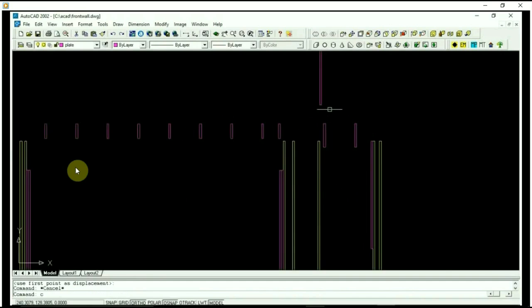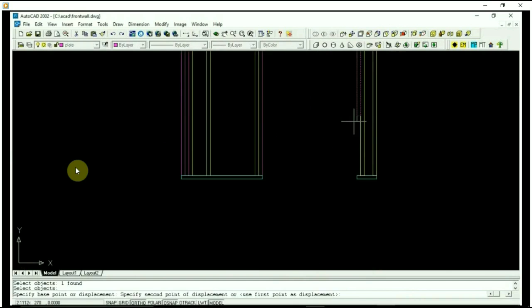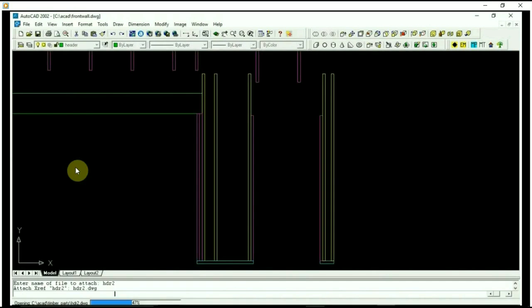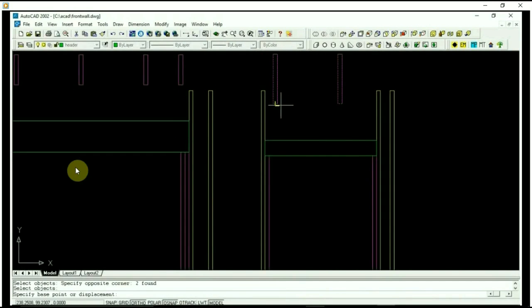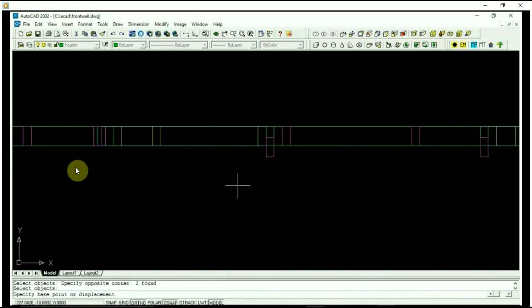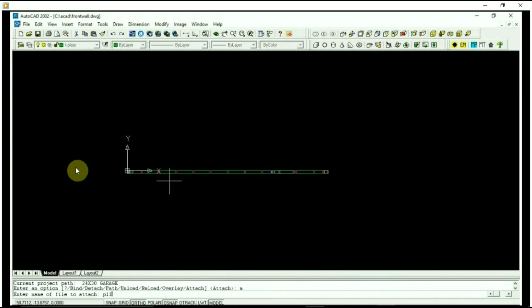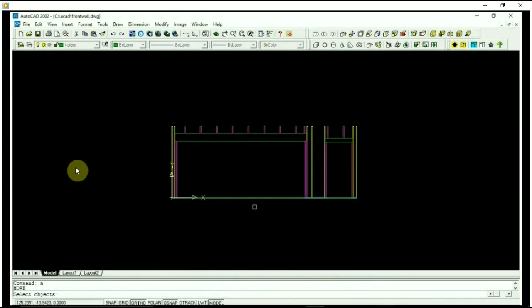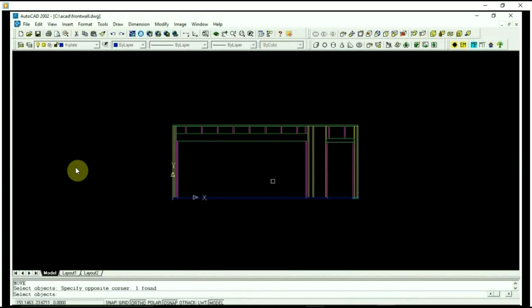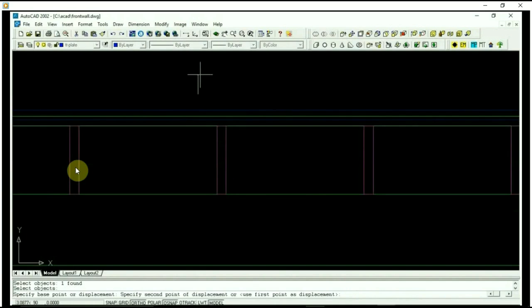So what I do is the AutoCAD standard: when I open up the template drawing, I'm basically looking down on the building. So for the walls, I'm looking down at the plates, and I'm looking at the studs in section. What I do when I place my parts is I always place them in profile. So when I place them, I'm looking at their width and their length, and their thickness is into the screen. When I place the plates, I'm looking down on the building, so I'm seeing those in profile.